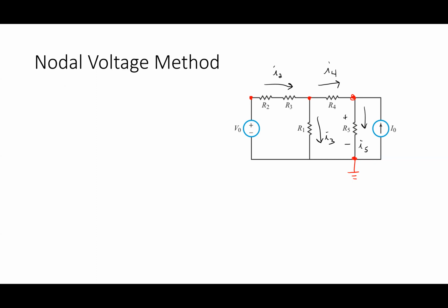You set one to be ground. Okay, and we use that term ground. All right, we don't talk about that much, but ground is that middle, it's the little pin on the outlet. And I'm just kind of arbitrarily making it here, but any real circuit you build, you actually have a connection to the earth, like to the dirt, right? And you make that connection via a pipe or something into the dirt. All right, so any real circuit that you build, you have a connection to ground. That's why we call it that. And ground is defined to be 0 volts. All right, so we use that symbol for it typically.